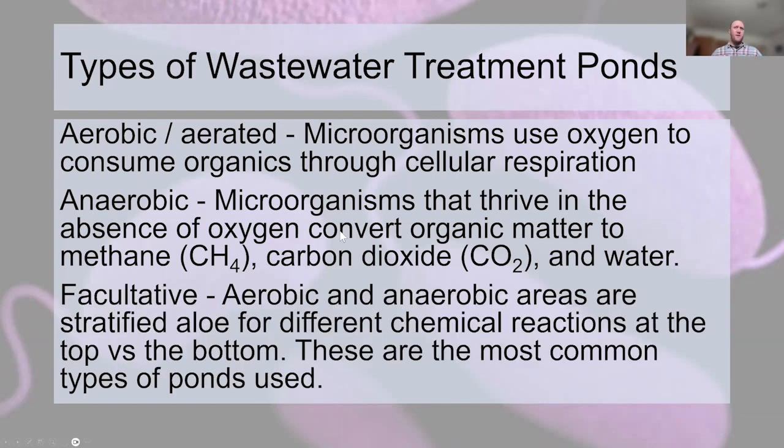And then facultative. This really is a combination of both, the aerobic and the anaerobic. The lagoons are stratified, so you have oxygenated on the top, and on the bottom is this anoxic zone. There are different chemical reactions, different functions going on in these different areas. These facultative lagoons, utilizing this facultative bacteria, these microorganisms, really are the most common because they do both in one.